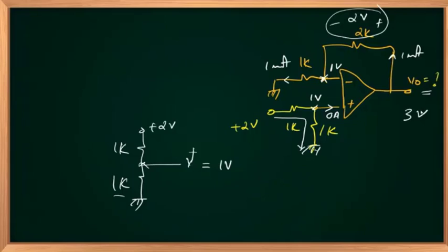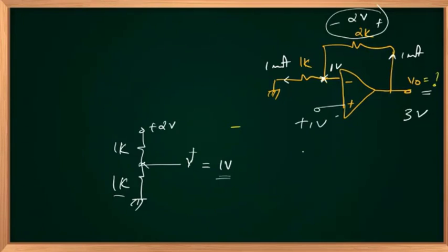Right. Very good. Or still, if you're having any confusion, V plus is equal to 1 volt. So this entire circuit can be replaced with our old circuit with 1 volt. 1 volt multiplied by 1 plus R2 upon R1 is my V out. 2 by 1 is 2 plus 1, 3. 3 into 1 is 3 volts. Both ways it is correct. But with the earlier one, looking into the circuit, you can identify V out. Is that clear? Okay. Anybody, any problems? Any issues?